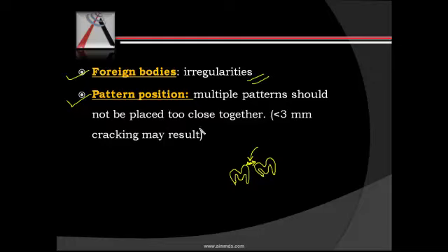If these two wax patterns are placed too close together, they may crack, and that may be seen in the investment between the two wax patterns. So if the space is less than 3 millimeters, the chances of cracking are high.